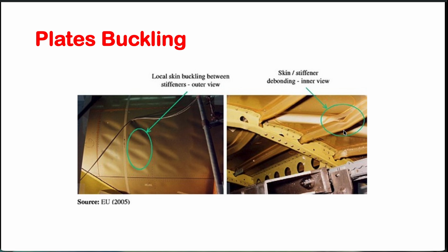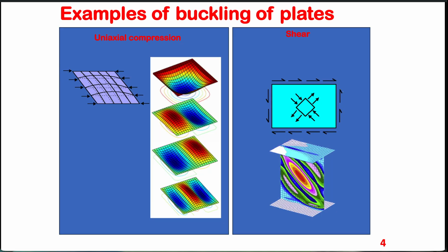So the material here has not yielded, there is no fracture yet, but we do see buckling. We have analyzed the Euler column buckling, so we already know that buckling usually happens before the yield stress of the material, which means that it is an important concept that we need to definitely bring into our analysis.